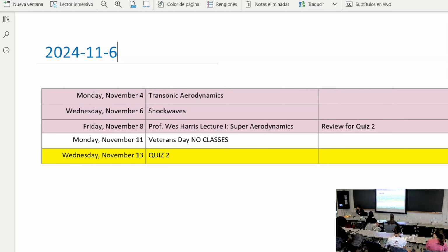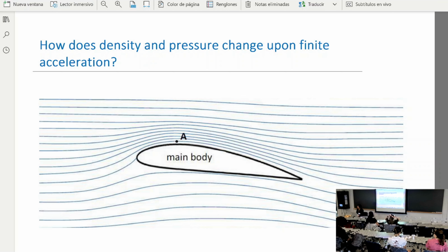Okay. So last lecture we looked at how we go from the geometry of a flow, like a flow stream contracting or expanding, to how the pressure coefficient changes. For subsonic flows, as the stream contracts, the pressure coefficient decreases. You did the calculation on the board: upon a contraction of 1%, the pressure coefficient decreases by 0.02.